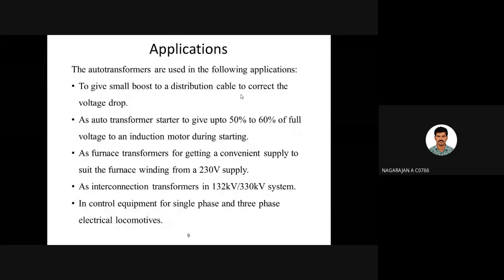When you keep it in position 5, the entire resistance connected in series will be cut out. The entire supply will go to the fan. So now the fan will be running at its maximum speed, since it is receiving the entire power. Okay, so this is the case of an auto transformer. When you keep the center tapping position at 0, you will be getting 0 voltage on the load side. When you adjust it to the 230 maximum side, you will be getting maximum voltage.